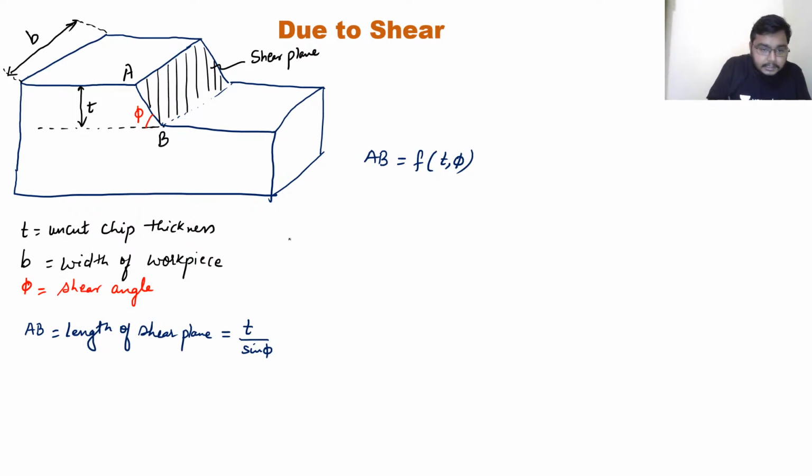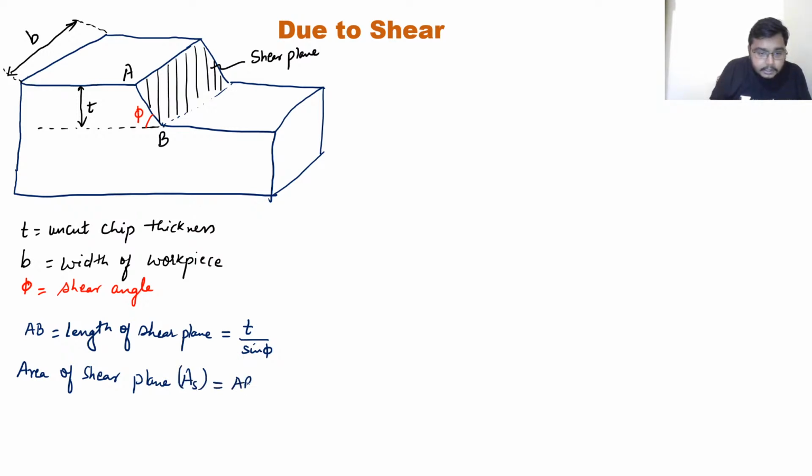Now please tell me, this is my length of shear plane, so what would be the area of shear plane? That would be AB into width of workpiece.